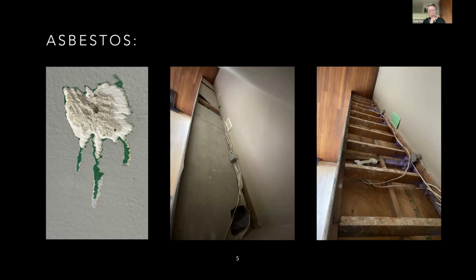That little image on the left is us testing to see if asbestos was in any other areas of the house, either in the walls, plaster or in the flooring. And everything was clear until we went up to remove those panels and then found vermiculite, which, horror story, is what can cause the cancer that is the fear of people inhaling asbestos, and it also upped the requirements for precautions during asbestos remediation.